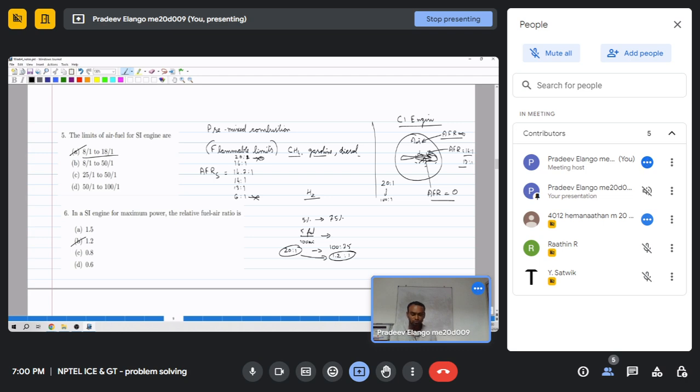So this is the flammability limit for hydrogen. So that means from the hydrogen tank, and here it is full air in the atmosphere, if it leaks a little, for a large region there could be a flammable mixture, because here the AFR is infinite, and here at the periphery it is 5%, and somewhere inside this region it will be say 75%.